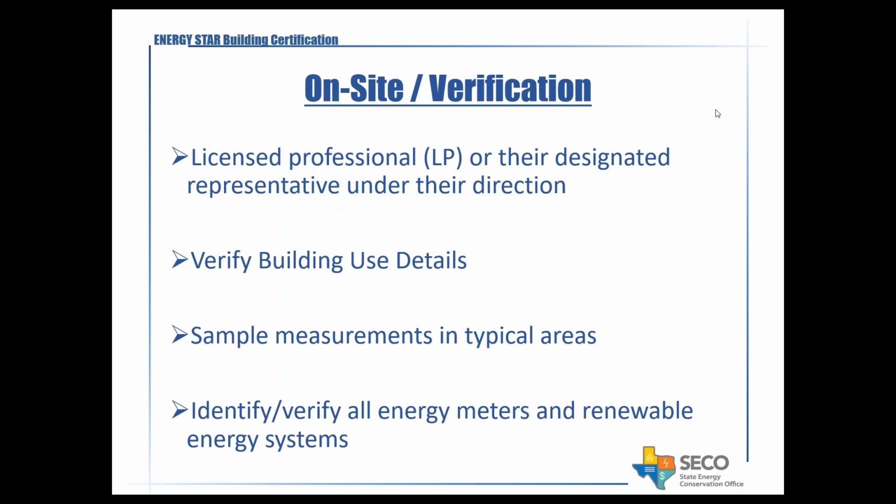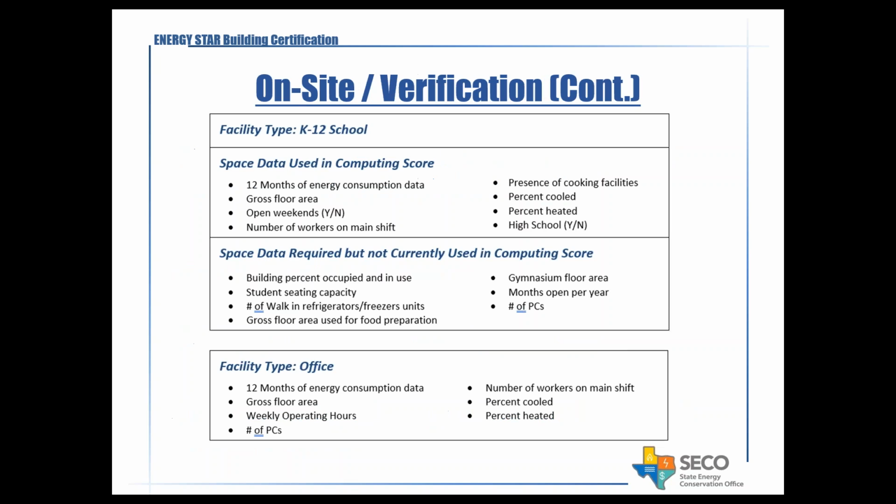So the next step in the process that we had overviewed is the on-site verification. So I just wanted to go over what's all involved during this on-site verification. The licensed professional or their designated representative will be checking all these details, and will be taking sample measurements in typical areas. They don't have to measure in every area, but I think just a sample is sufficient for the purposes of the verification. And then they will verify all the meters and the renewable energy systems on site, make sure they're all tracked in the application.